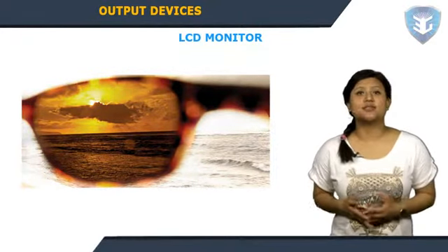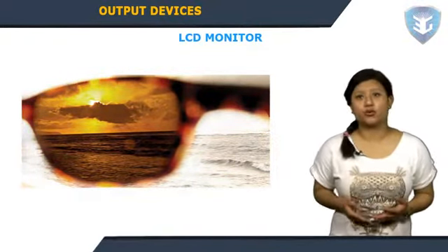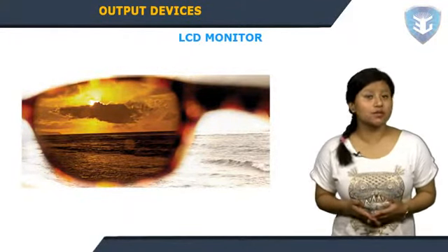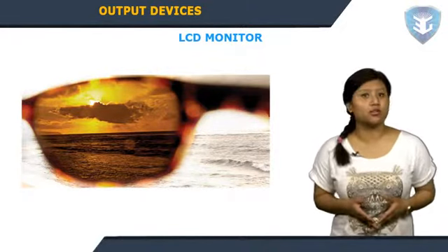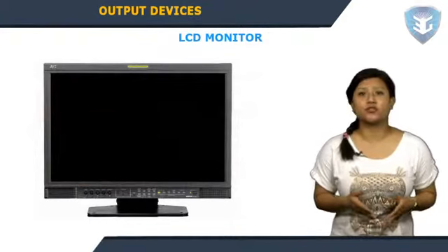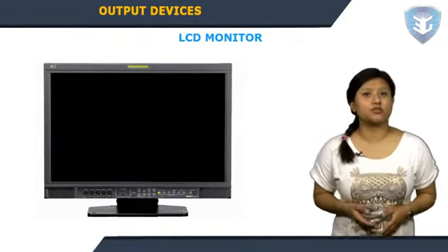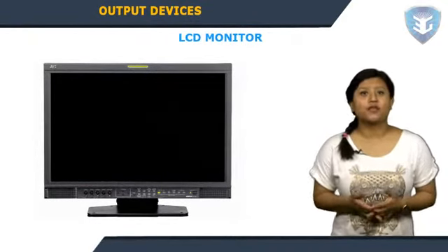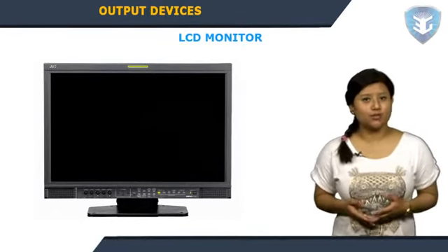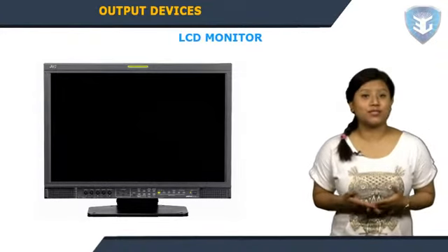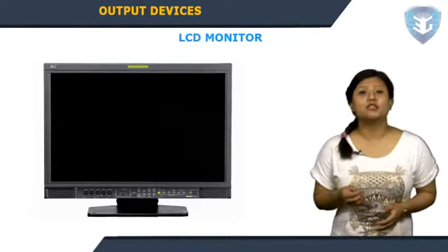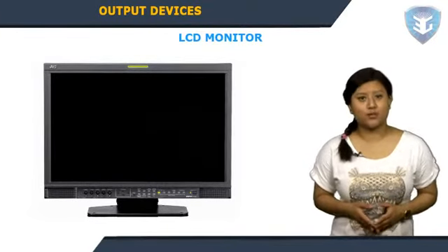An LCD monitor consists of 5 layers: a backlight, a sheet of polarized glass, a mask of colored pixels, a layer of liquid crystal solution responsive to a wired grid of XY coordinates, and a second polarized sheet of glass. By manipulating the orientations of crystals through precise electrical charges of varying degrees and voltages, the crystals act like tiny shutters, opening or closing in response to the stimulus, thereby allowing degrees of light that have passed through specific colored pixels to illuminate the screen, creating a picture.